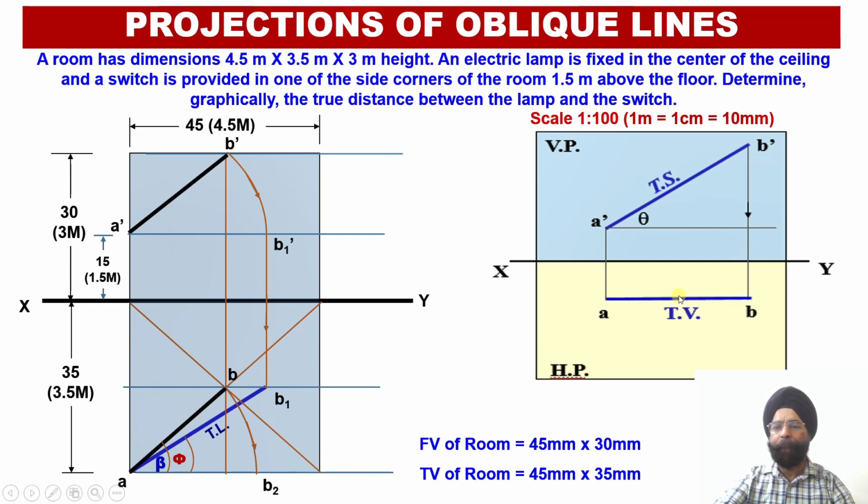So once this apparent length projection happens to be parallel to the vertical plane, through the point B2, we are going to draw a vertical projector onto the vertical plane and extend it up to the locus line corresponding to the point B dash, and wherever this intersection happens, we are going to obtain the point B2 dash over here.